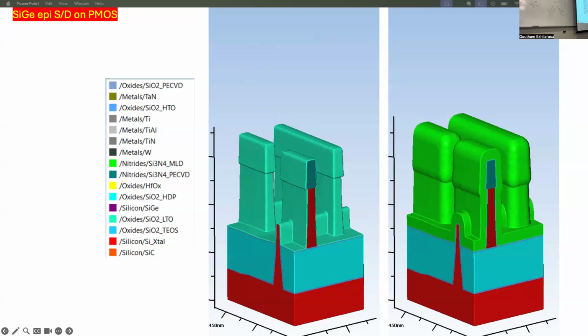Okay. Right? So it's a little difficult to draw this because it's three-dimensional, but this is going in this direction, right? This gate is going orthogonal to it. So if I was to draw, it's something like this, right? And then what I'm going to do is deposit in this orthogonal direction, and then the sidewall spacer will come like this. So first you deposit, and then when you vertically etch down, it's going to create the sidewall spacer on the gates. So the process can change? No, it's exactly the same process.